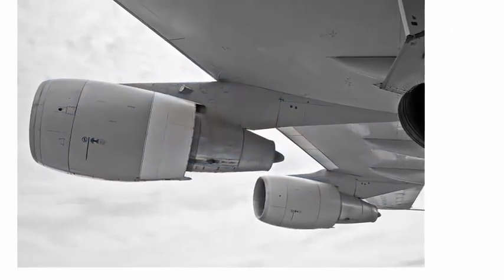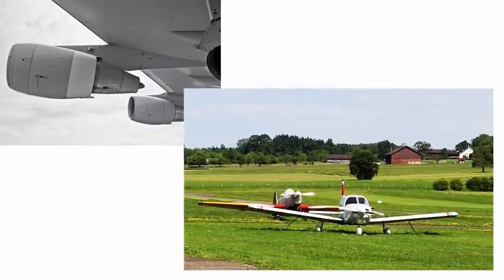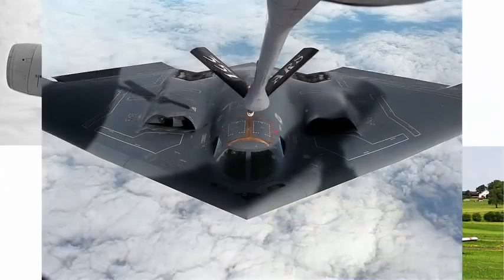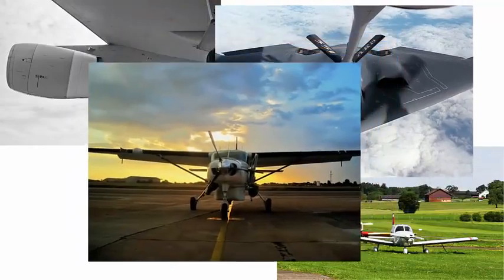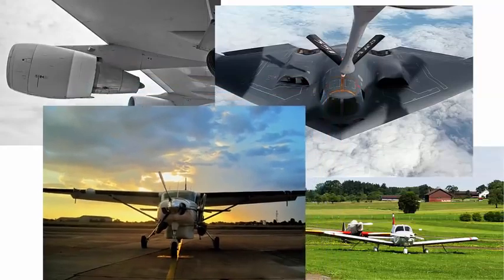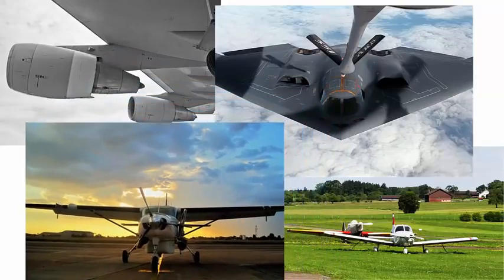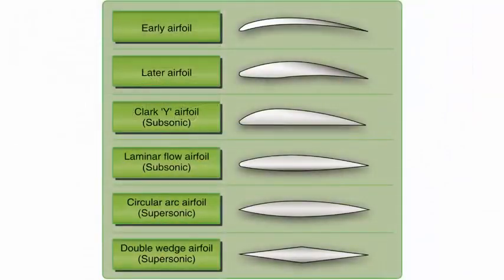Different airfoils have different flight characteristics. Many thousands of airfoils have been tested in wind tunnels and in actual flight, but no one airfoil has been found that satisfies every flight requirement. The weight, speed, and purpose of each aircraft dictate the shape of its airfoil. The most efficient airfoil for producing the greatest lift is one that has a concave or scooped-out lower surface.